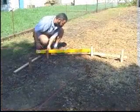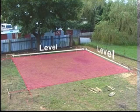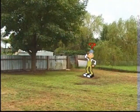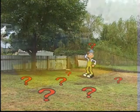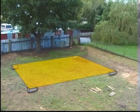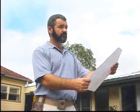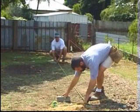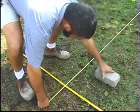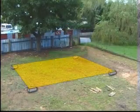On most sites, it is necessary to find the high point of the ground on which the structure will actually sit. Before this can be done, the approximate location of the building needs to be established. This can be done by inspection of the building block in conjunction with the site plan. A quick measurement gives the approximate location of the corners of the building. This gives an overall idea of the job. A levelling procedure gives the highest point of the ground covered by the building.